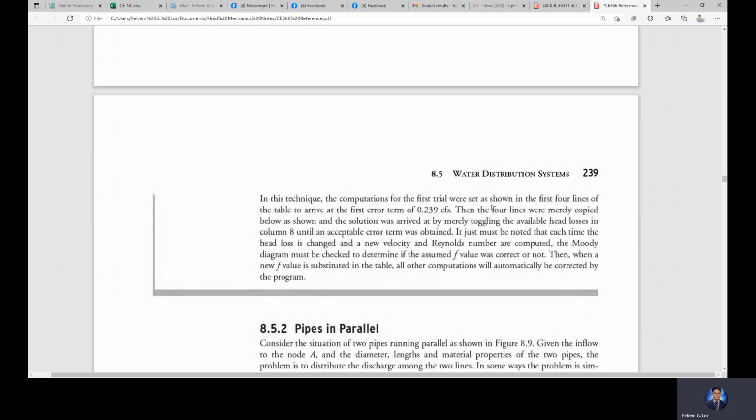Actually in design, in fact when I design, at first it is trial and error, but nowadays I usually do just a first trial and second trial, because it's almost memorized. Given the load, the distances, and the height, you memorize the dimension of the beam and which reinforcing bars to use. So you just check if your assumption is right, whether it is too large or too small. So maybe a maximum of 3 trials only. That is how it is in actual practice.